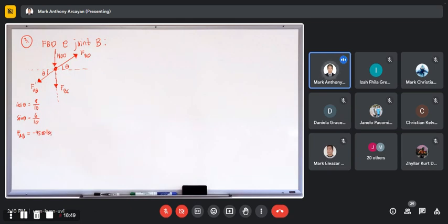If you correct your direction for FAB, following the true answer from the previous computation, you change its direction. If you don't correct it, you use the negative value. If you correct it, since it is tensile, when you draw it in the FBD towards the joint, do not use the negative answer but rather the positive.